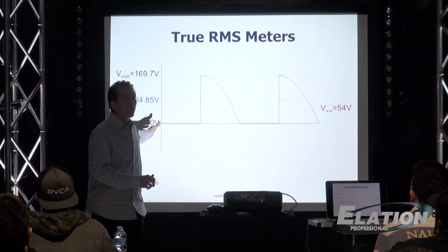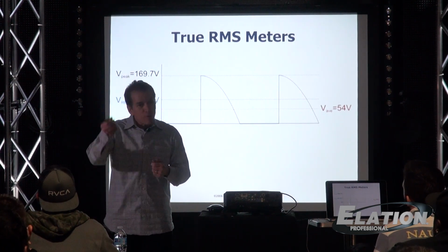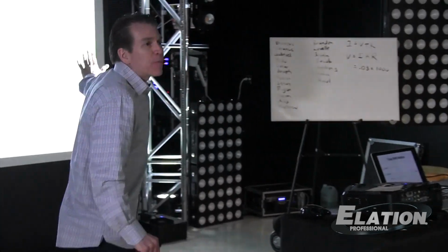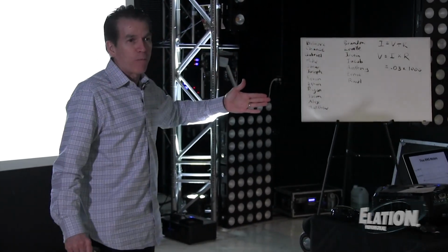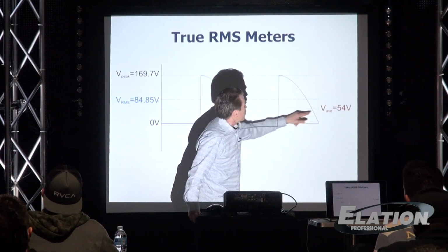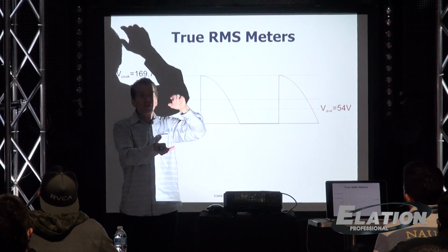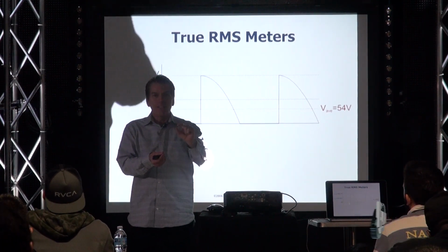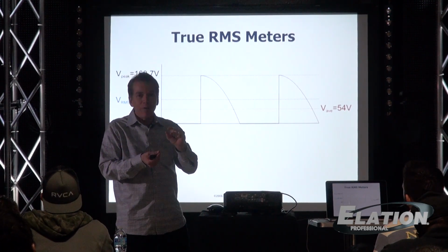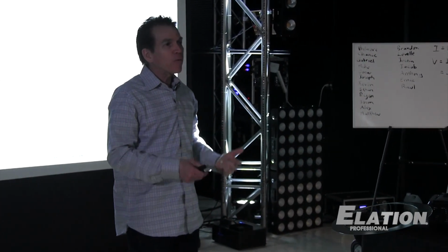This is an example of a waveform that's been put through a dimmer. If you dim it down, this is dimmed 50%, it chops up that waveform. When it does that, the difference between the average value and the RMS value grows. And your meter doesn't know that. So it still has that little multiplier, so you start to get reading errors. And you get wrong readings.